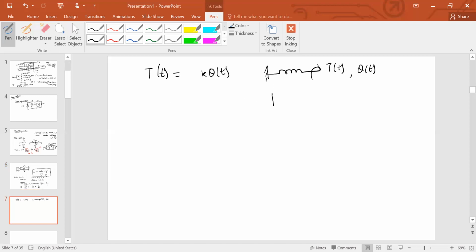Similarly, when I have a rotational dashpot given by this, where a torque is applied, the relation is given by, let's call this spring constant K and this as D to distinguish it from the linear one. Spring constant is still the K. You might use some other symbol, but at least to distinguish between the dashpots, let's use D here. So this is T = D theta dot.